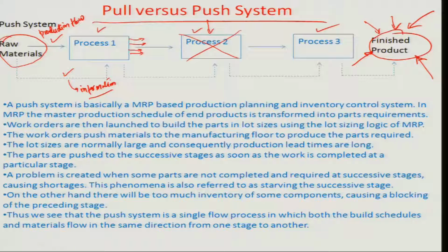There is no stop to that flow because you are driving process 1 on the basis of the push system, which already has a planning horizon defined, and therefore there will be a pile up. Process 2 is not able to absorb any more and process 1 is still sending the material. This is a natural consequence of an imbalance caused by the defect in process 2.